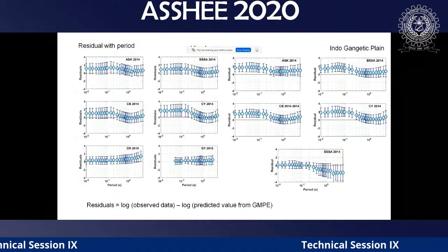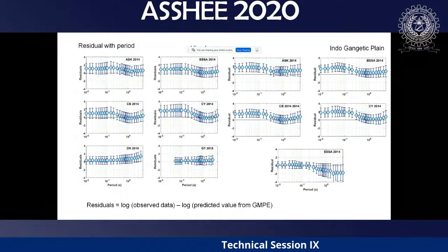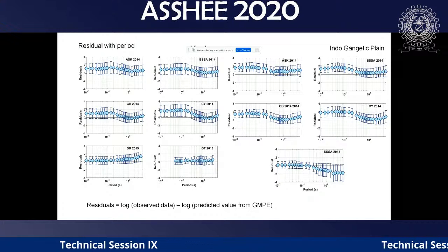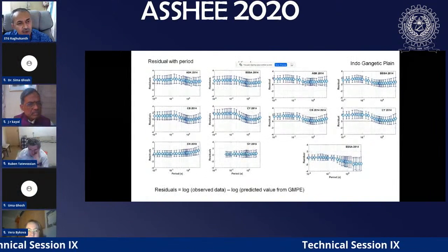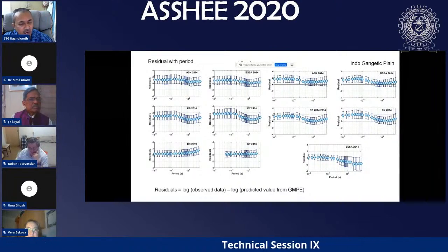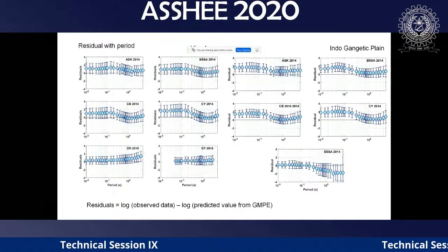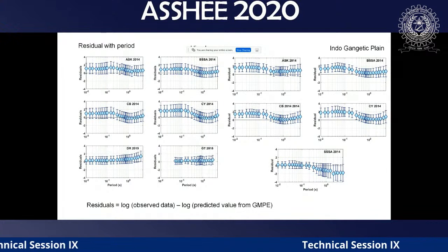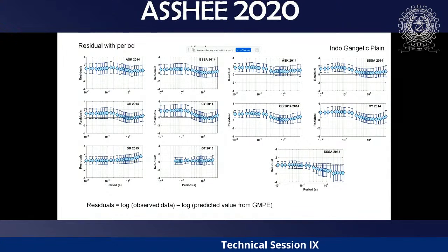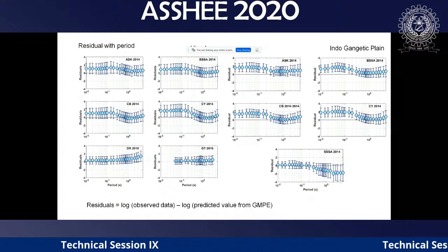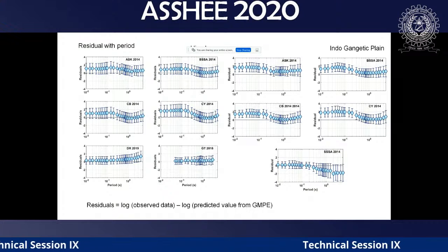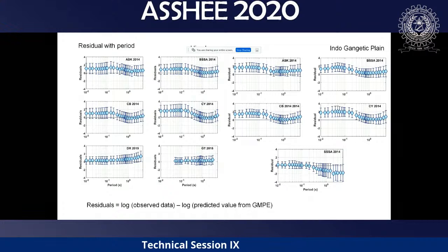So using this data, because we have to do a logic tree kind of approach, multiple GMPEs have to be used. These GMPEs should come from a similar tectonic background. I am just showing here the Himalayas and the Indo-Gangetic basin. We have adopted the NGA-West2 equations here, so Atkinson, then Boore, Campbell, and these equations have been there. And then we have our own equations also. One has been developed by I.D. Gupta, Trifunac, one equation. Then we have my own equation, which we developed from this data set itself.